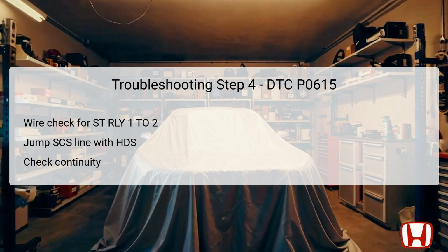Disconnect the relevant connectors, including the PCM connector A50P and the relay circuit board connector A8P. With these connectors detached, check for continuity between the designated test points in the circuit. This check is crucial. If continuity exists, it indicates the wire is functional, implying the issue could lie in other connected components, such as the PCM. If continuity is absent, this leads to a diagnosis of an open circuit that must be repaired.